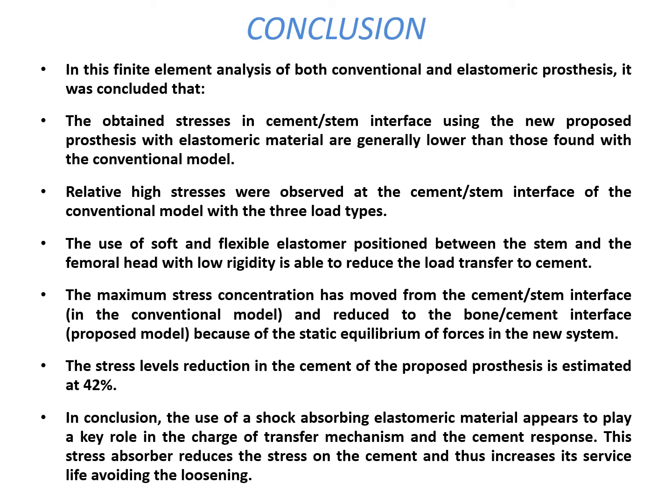In this finite element analysis of both conventional and elastomeric prosthesis, it was concluded that the obtained stresses in the cement-stem interface using the new proposed prosthesis with elastomeric material are generally lower than those found with a conventional model. Relatively high stresses were observed at the cement-stem interface of the conventional model with the three load types. The use of a soft and flexible elastomer positioned between the stem and the femoral head, with low rigidity, is able to reduce the load transfer to cement.